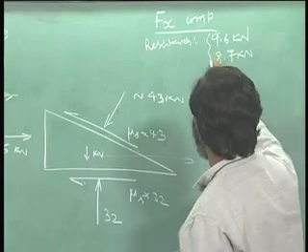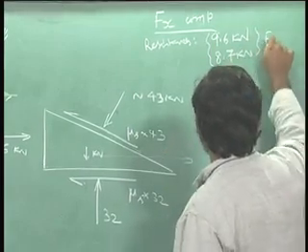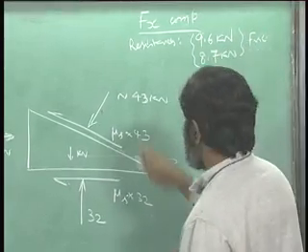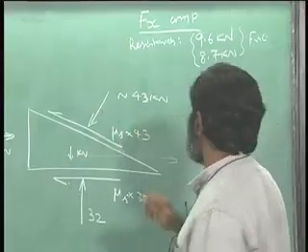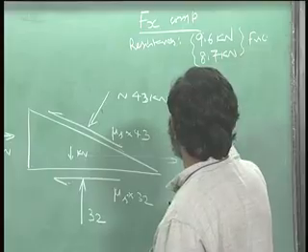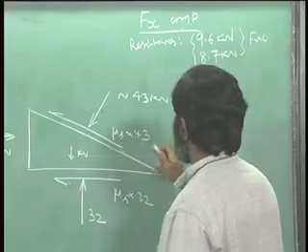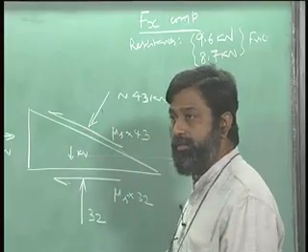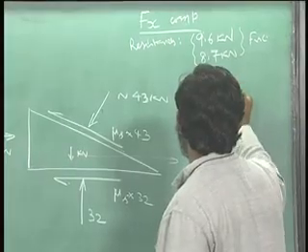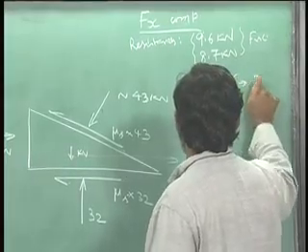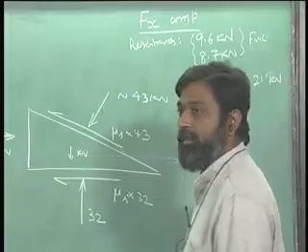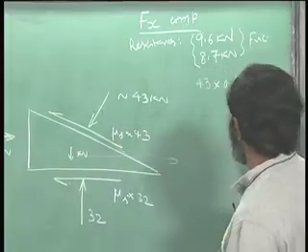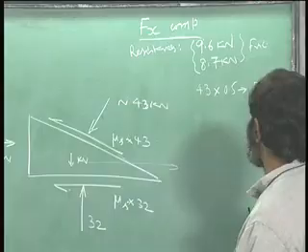So these are the frictional resistances. Then the other resistance that comes in is due to this normal reaction, and that is 43 times sin 30, okay, and roughly around 0.5, that gives me 21.5 or let us say 21 kilonewtons, okay. So there is a resistance in terms of the normal reaction which is 21 kilonewtons.